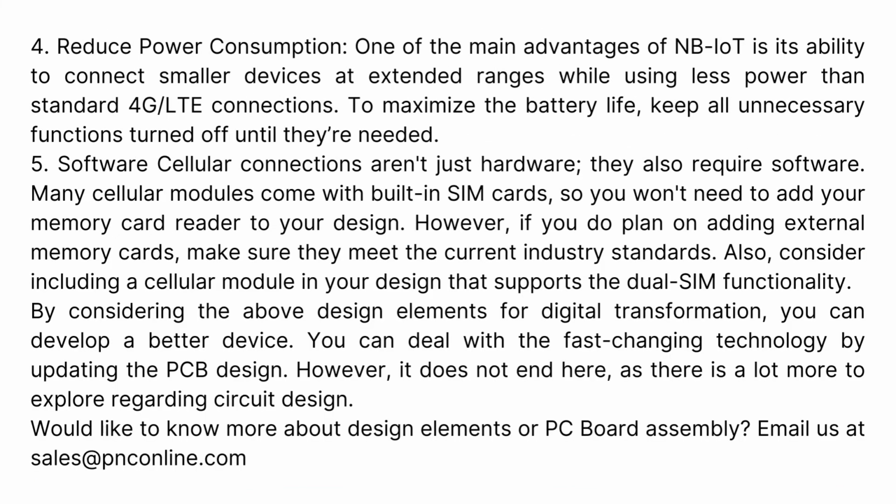4. Reduce power consumption. One of the main advantages of NB-IoT is its ability to connect smaller devices at extended ranges while using less power than standard 4G/LTE connections. To maximize the battery life, keep all unnecessary functions turned off until they're needed.